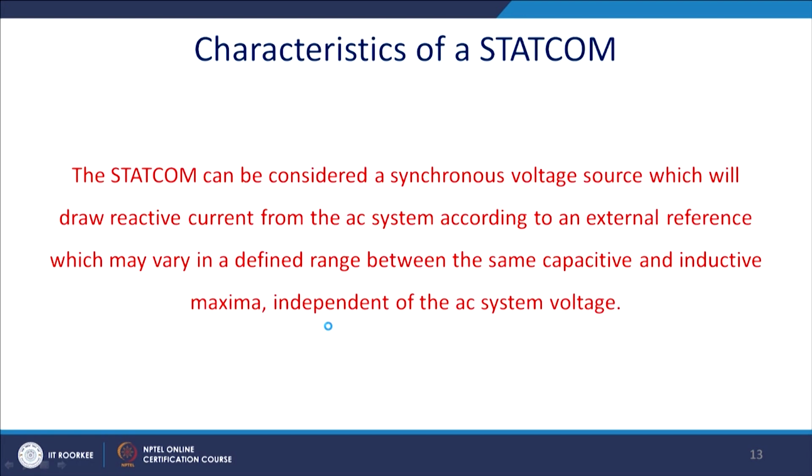So, what are the characteristics of the Statcom? Statcom can be considered as a synchronous voltage source which will draw reactive current from the AC system according to the external reference, which may vary in a defined range between the maximum capacitive and the maximum inductive, and independent of the system voltage.